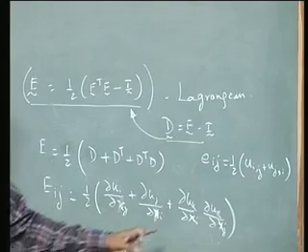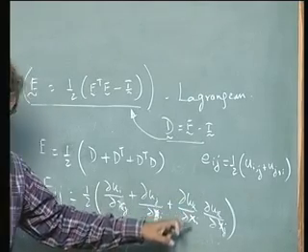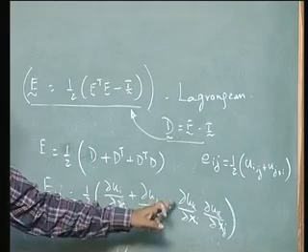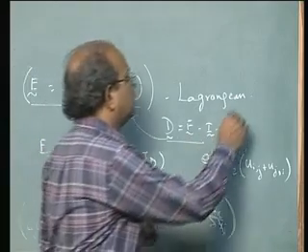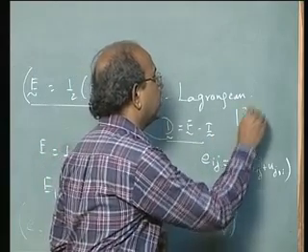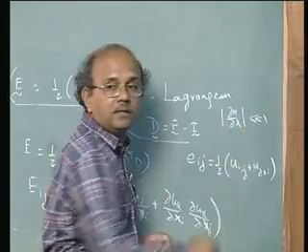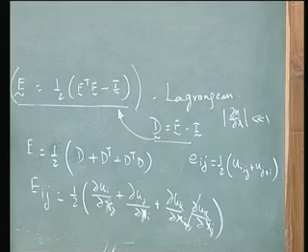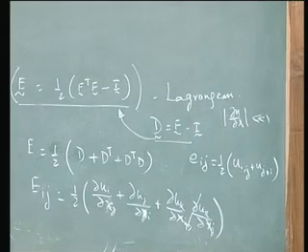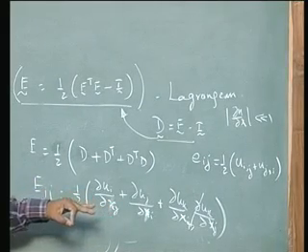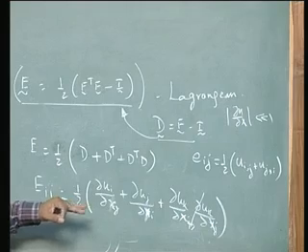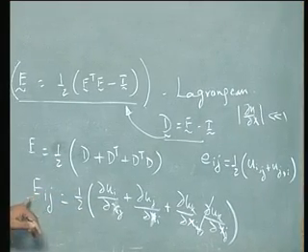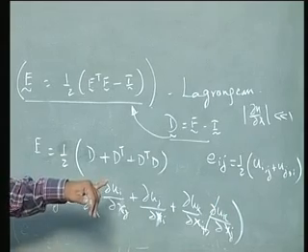And number two, when the gradients of displacements are also very small, such that dou u by dou x is far less than 1, then this term goes off. So what we say is we have linearized these quantities. Linearization of my displacement would result in capital Eij being equal to small eij.